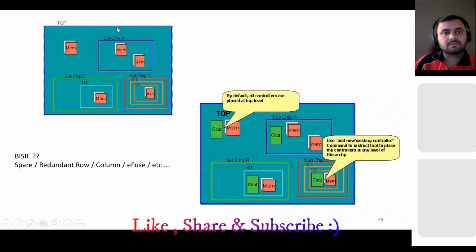Then you have this top, you have a sub chip, you have a sub block. As I told, memories can be at the top level, at the block level or at the sub-block level. So you need the controller to generate the test signal, test address, test data and so on. But the thing is, you must be thinking why we cannot test the memory using one controller. Why do we use multiple controllers? This is because we have different types of memory: single port, dual port, multi-port memory, and these memories may not work at the same frequency.